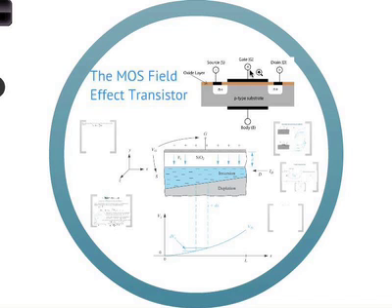You apply, in this case, a positive voltage. You push the holes away, you attract the electrons, and make an N channel. So you make an electron channel, and then the current can flow. The more positive you make it, the more electrons there are, so current will increase until pinch off happens. Pinch off in this case is where the depletion region eats into the inversion region.